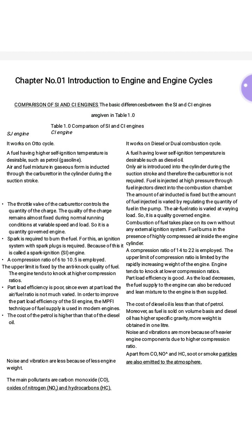In an SI engine the charge is induced with the help of the carburetor, and with the help of the throttle valve, that is the butterfly valve, we can regulate the quantity of charge. The quality of charge remains the same; only the quantity may be increased or decreased as per the requirement. Hence it is called a quantity governed engine.